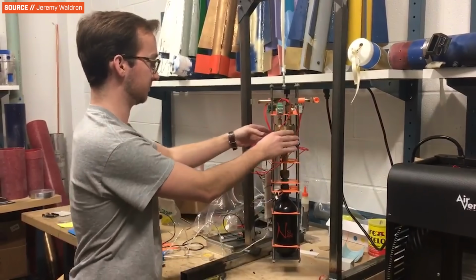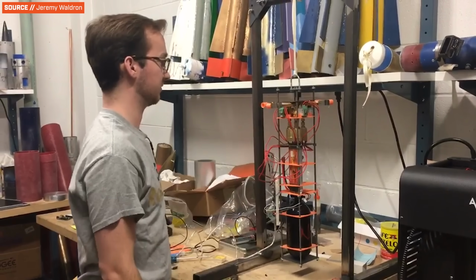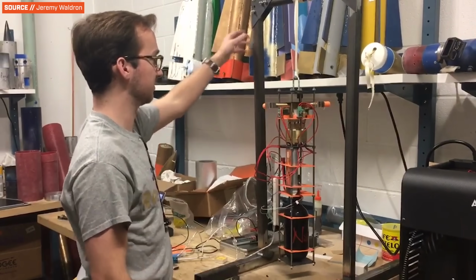So again, that's actually another huge limitation of cold gas thrusters, is just in the overall enthalpy, or really the lack of heat in the system, which prevents them from really being that efficient. However, they're very simple and extremely reliable and really only have one moving part, a simple valve. That's about it.